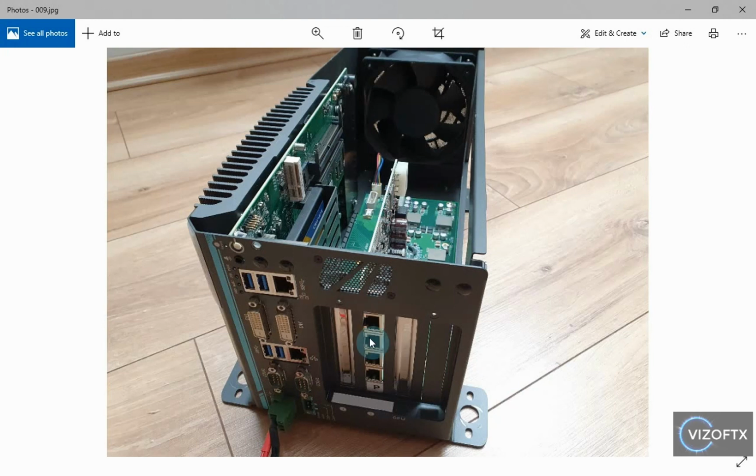Sometimes the video card GPU needs the connector too, because the PCI Express X4 can deliver 25 watt power without any problem, so for cameras of 5 watt each it would be about 20 watt. It means that we have a safe reserve there. If we use the X16 slot, we have up to 75 watt. So if you need more power, you can either switch to the X16 or use this power port. We then connect the cameras separately using Ethernet cables directly to this Ethernet card.